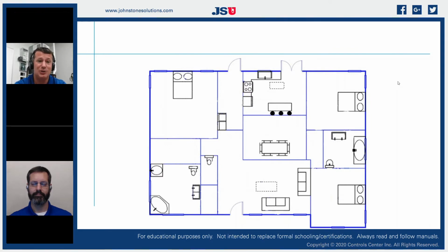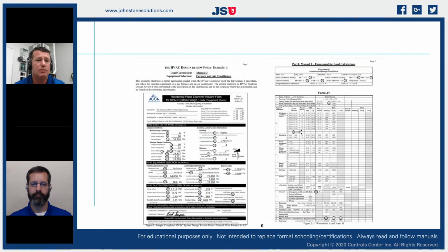Now we're talking about using R30 walls, R90 ceilings, and low-E windows that are triple pane. We're talking about very expensive materials, but we can actually produce a 1,500 square foot home that can be cooled on 5,000 BTUs. Big difference from our previous calculations, right? So it's all about understanding the materials that we're using and how much heat we're gaining and how much heat we are rejecting.